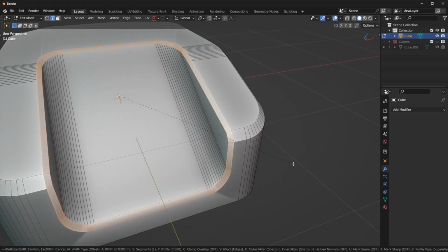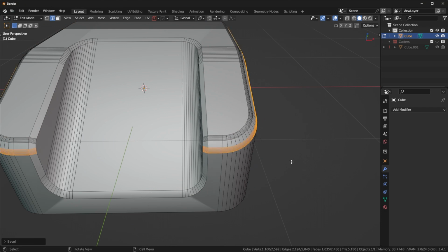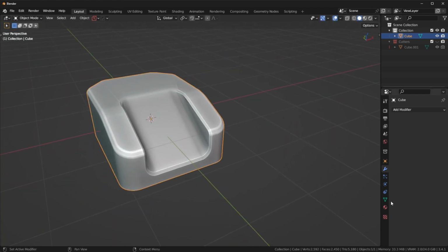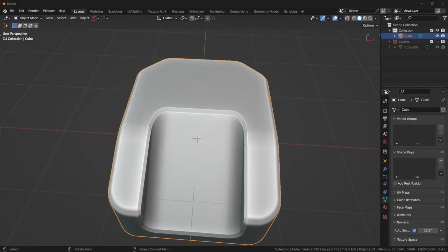Obviously, I could get away with a chamfer here, and I could get fancy and then bevel this area and then maybe bevel this area. But just keep that in mind if you choose to do things like this. It is definitely going to affect how your overall model looks. Now, make sure in situations like this, you also adjust your auto smooth to make sure it picks everything up. Now, let me show you an example where you could actually utilize concave chamfers. There are ways to get away with this. Like I said before, it's more of a feeling. You'll develop this feeling as to whether something fits or not.